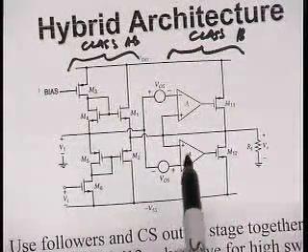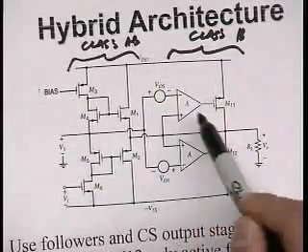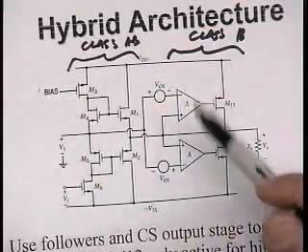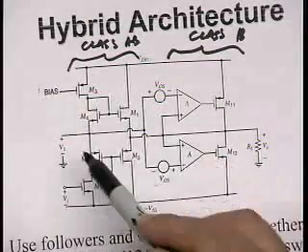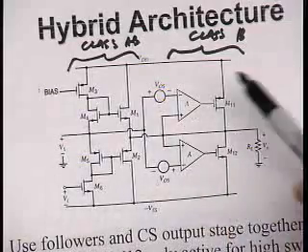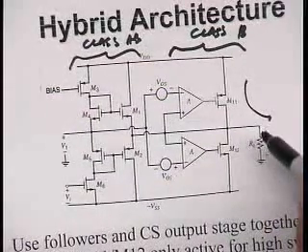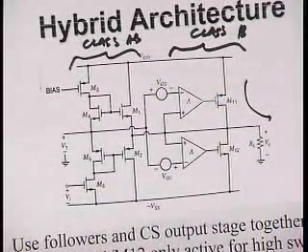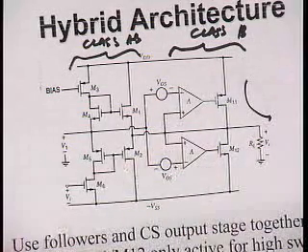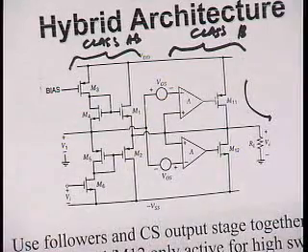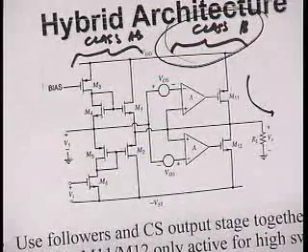It's not even there. And so this offset voltage doesn't even matter. Gain times offset voltage is still not enough to turn this device on. So for small signals, I just have a normal follower. As the signal gets larger, these turn on and deliver the current when the voltage is close to rail. And so then I've solved actually both problems. Of course, it costs me a lot of power, right? I've got two parallel output stages now. But the power is only coming when I need it because I run the second stage in class B mode.